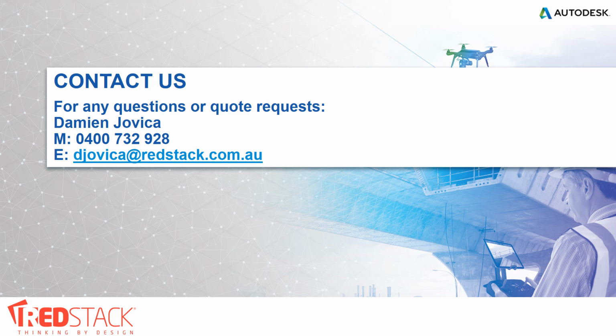Scan regions, yes, you can attach scan regions into Revit. So it's not the scan region; it's the RCP file. If you had an RCP file with 10 scan regions and you imported that RCP file, all 10 scan regions would come in. The workflow is, let's say I want scan region 3, you would save as, with the visibility on and off, and bring that in separately.